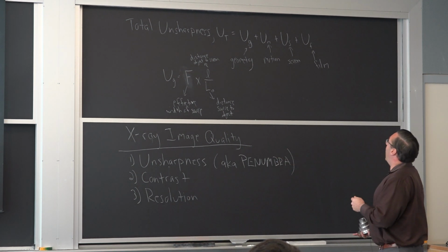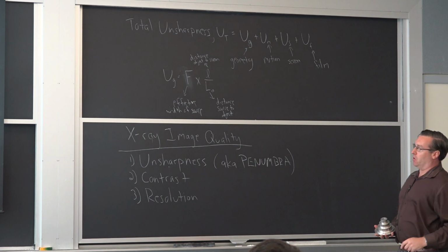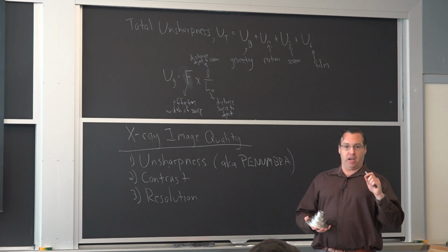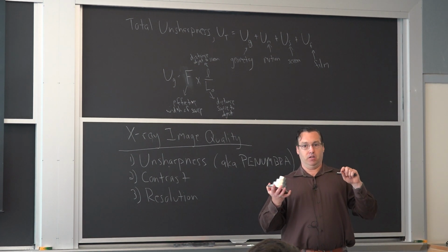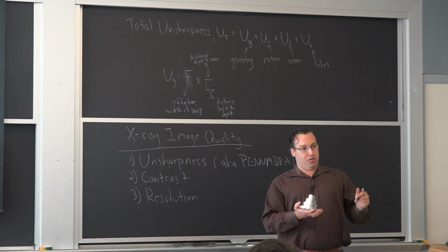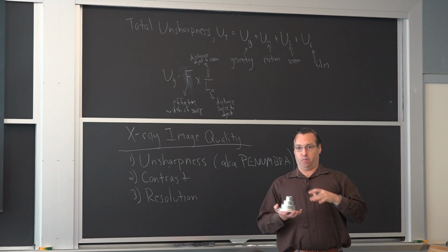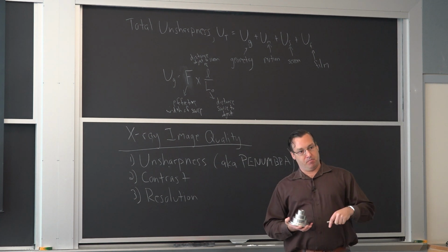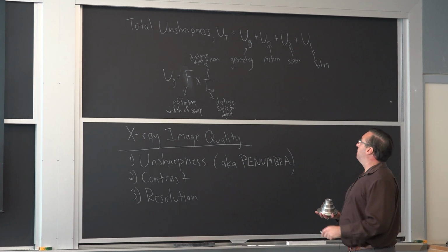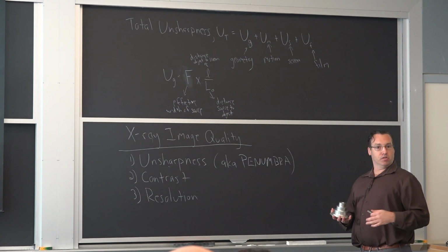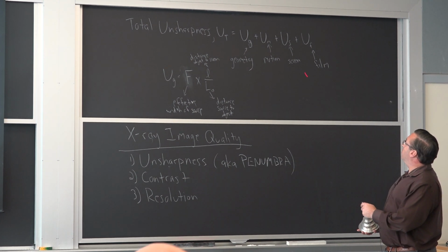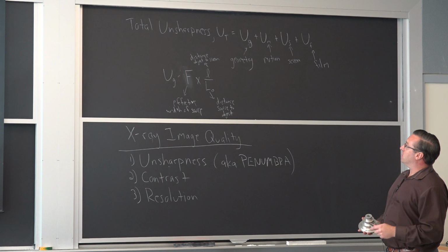And then the last factor is the film itself. There is some degradation if you're doing digital radiography, the more times you use that film. If you're using it 3,000 or 4,000 times, there is some degradation of the film itself just from multiple uses in service. So that can also be another factor of noise.